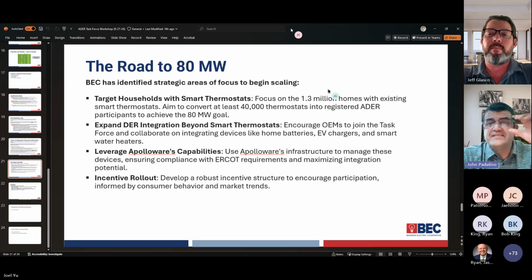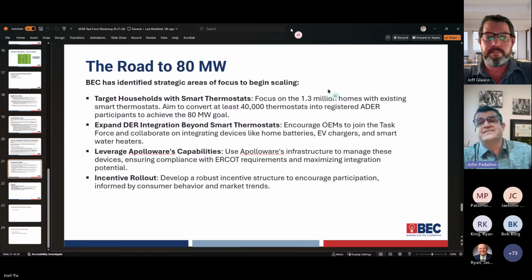Yeah, the device is essentially the same price as the electric meter that goes out there today, but the device can do a single phase or 3-phase system, and it can measure up to 480 volts, can take 15 channels, and so we could monitor a variety of devices, which I think is the goal ultimately, where a home doesn't just have a battery.